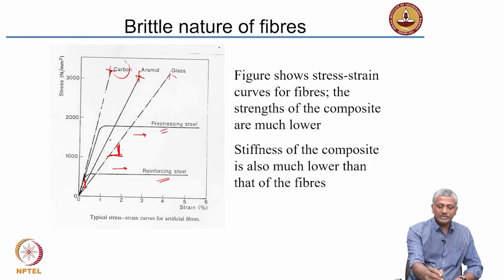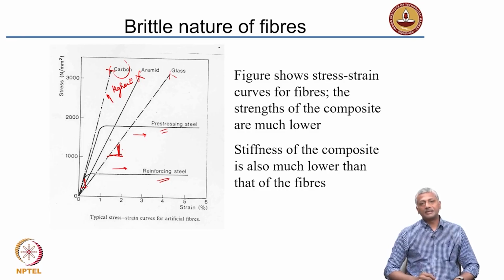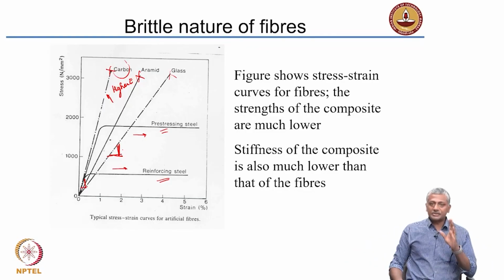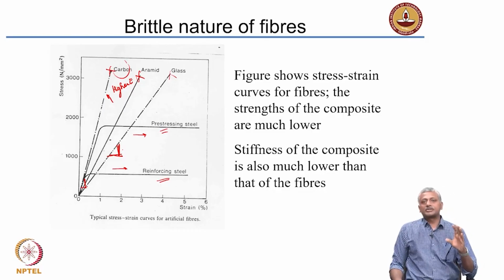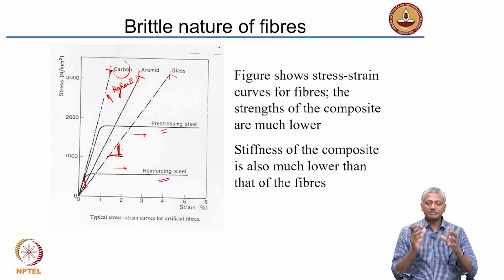When you go to carbon fibers, stiffness increases, closer to that of steel, but the problem is its extremely brittle behavior, with simply no plastic deformation before failure. In construction we always want to design structures to have a ductile and slow failure. When you compromise on ductility, it is not really an acceptable civil engineering solution. So this is something you need to worry about when you start using alternative materials.